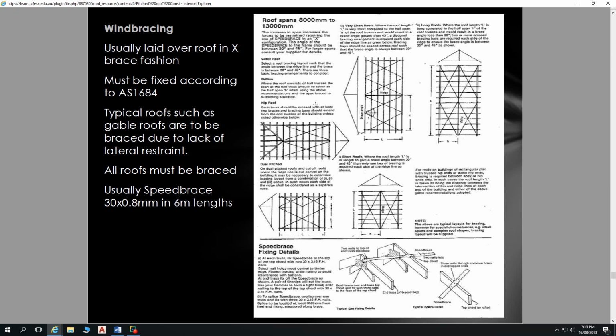So a force that wants to push the building over. That racking force is resisted by our bracing, so we can design our bracing to resist those certain kilonewtons of force. And the information for doing that is expressed within the timber framing code, but it's not the type of thing that you'll end up doing straight off the bat finishing study. So it's the sort of thing that you'll be designing with assistance from others initially.